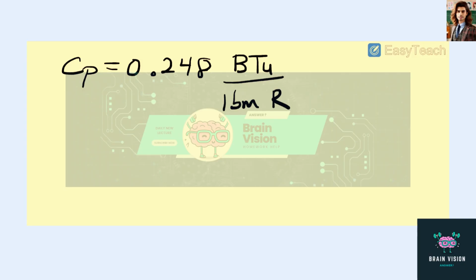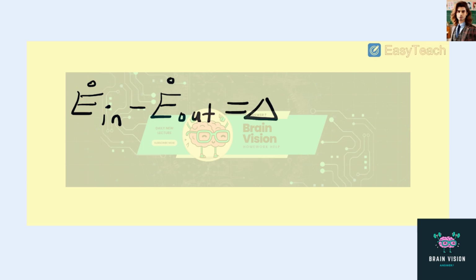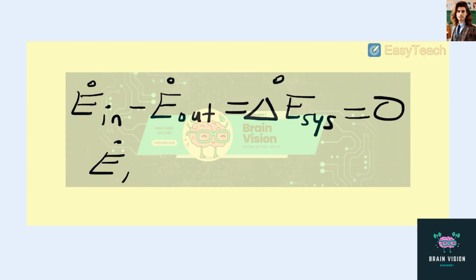And since this is a steady state problem and we're only dealing with one inlet and exit, our m dot at the beginning is going to equal our m dot at the end. And we're going to use the pipe as our system. So when we do our energy balance, we have the rate of the energy coming in minus the rate of the energy leaving is equal to the total rate of change of the energy in the system. However, since we said that this is a steady state problem, this is going to be equal to 0. So therefore, our energy coming in rate is equal to the rate at which energy leaves the system.